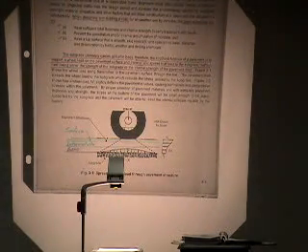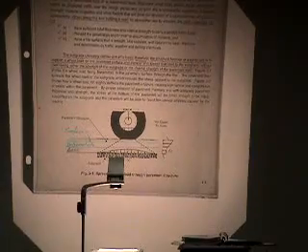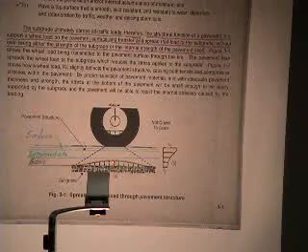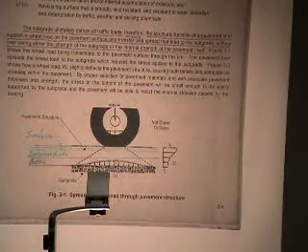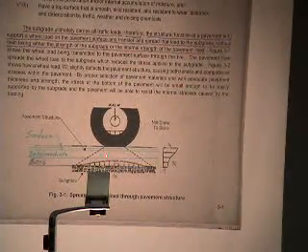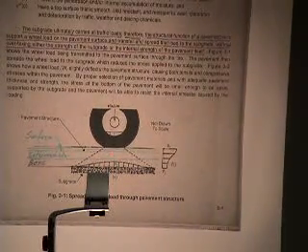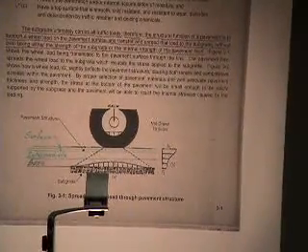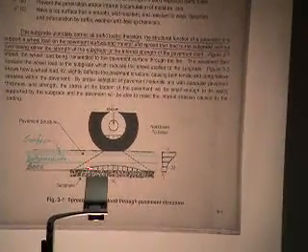And down at the bottom there, you'll see a drawing that shows the tire load being applied to the pavement structure. And ultimately, the subgrade is going to carry that load. But if the tire load was applied directly to the subgrade, probably you wouldn't be able to withstand very many passes before it started deteriorating. So the idea there is to put some pavement there such that the load is spread out as it is transmitted down through the pavement. It will spread out to the point that the subgrade will be able to carry the load for many, many applications.